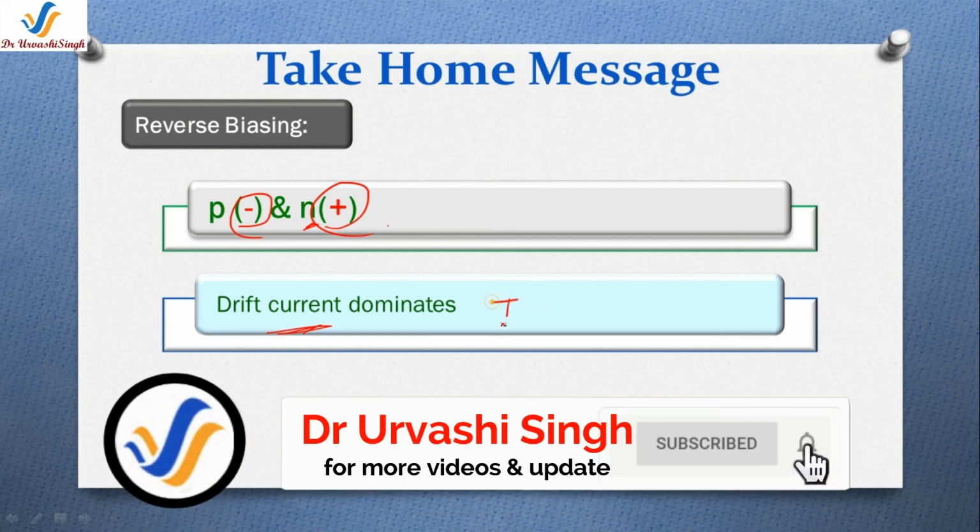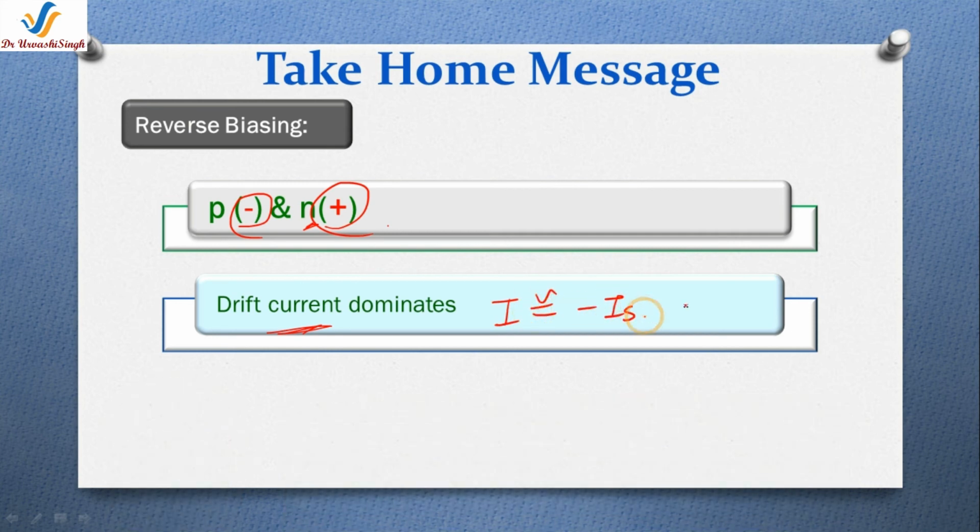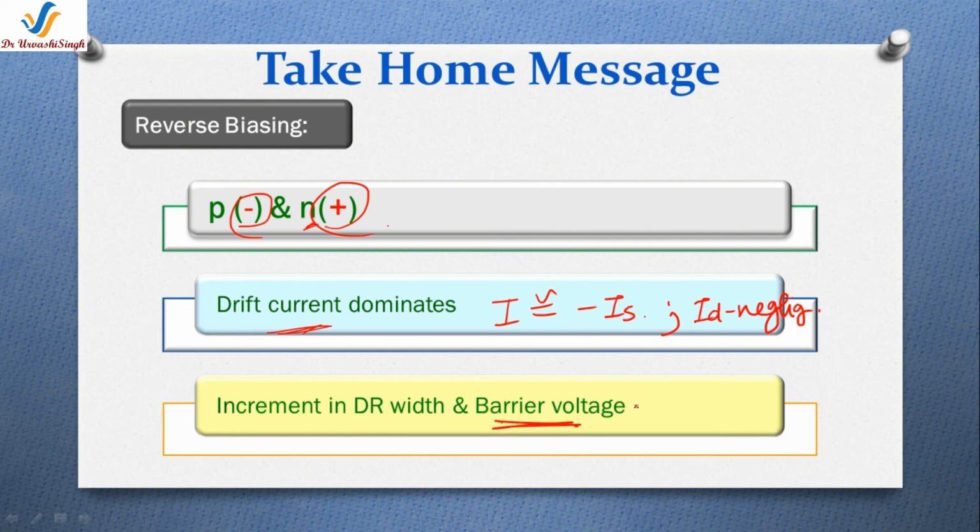So the current in the external circuit is almost equal to minus IES because the diffusion current is negligible in reverse biasing. Why so? Because in reverse biasing, the effective barrier voltage increases, and this will also affect the width, and so the charge or the depletion region both will increase.